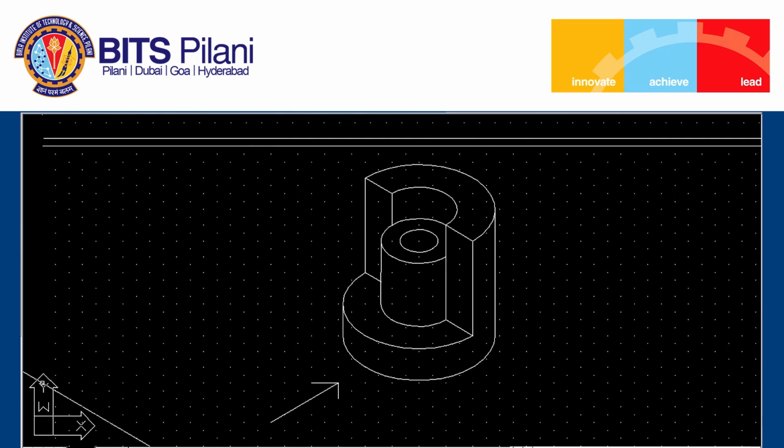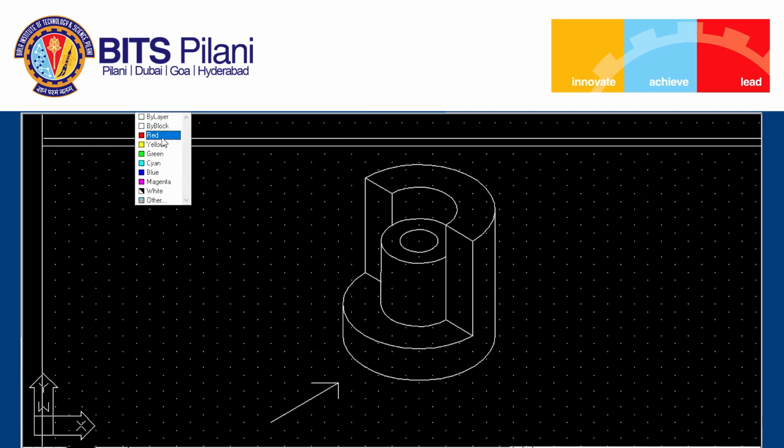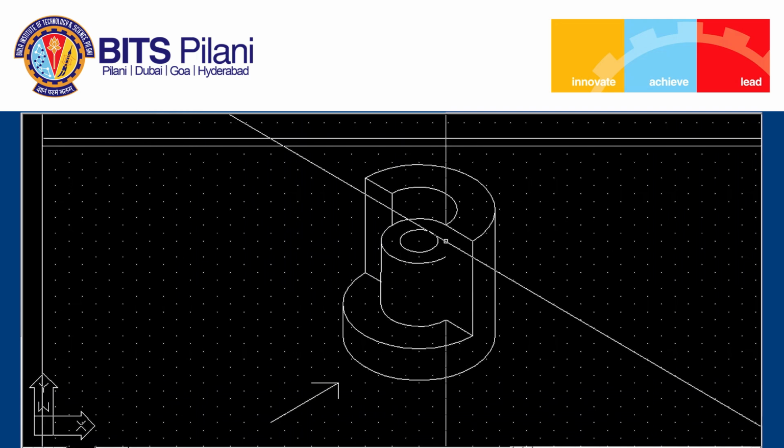Now, let us discuss one problem on the curved surfaces. So, the given object is a single piece object, and for the curved surfaces to find the dimensions we use the center line method, and the arrow indicates the direction for the observer to see the front view. So, the visible side view is the right hand side view, and we will follow the third angle method of projections. So, let us first find out the dimensions using the center line method.